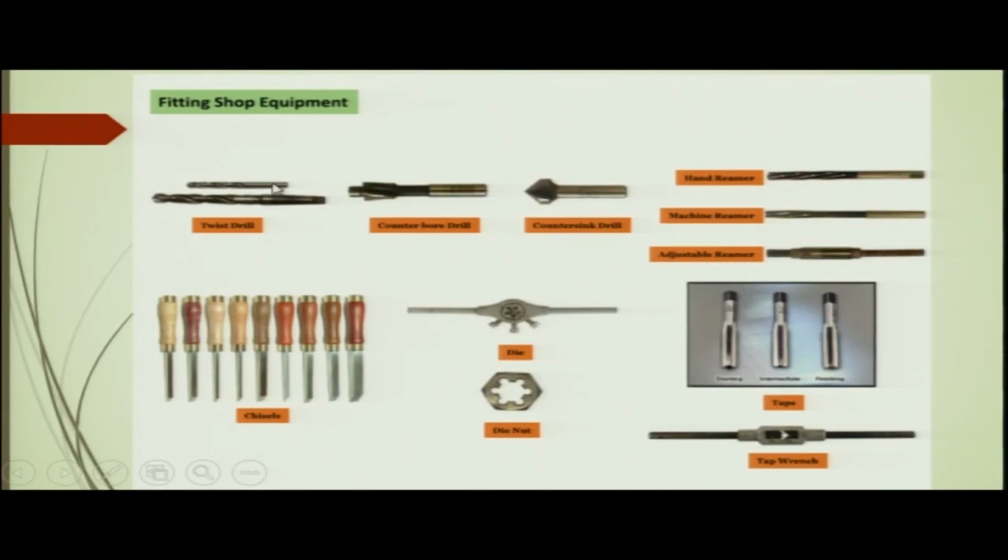In particular, normally there is a groove and a spring loaded ball. That spring loaded ball will be fixed in the internal groove and the hole made in the tool holder. So, this is just a snap fit, snapping the drill into the tool holder.